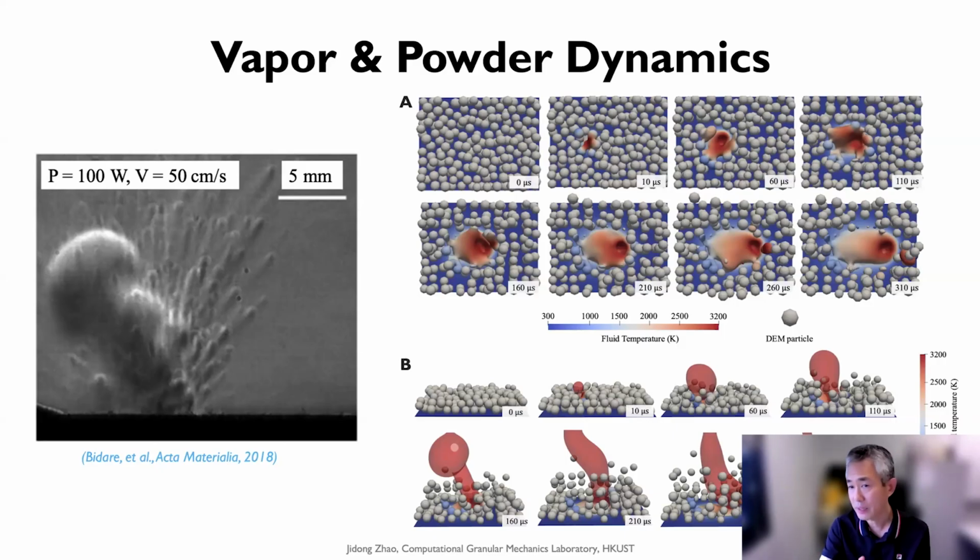If you don't have enough source of metal particles, the printing quality can be low. That's why it's important. It's not necessarily true that a higher laser power, a faster speed, or a lower speed generates better quality. Sometimes you really have to have a balanced strategy, choosing the proper power and proper scanning speed, because the ultimate goal is better printing quality.